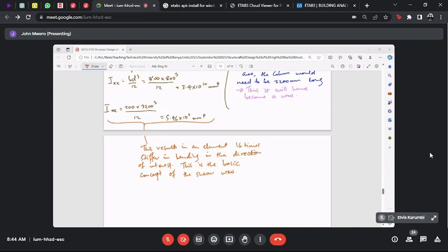And if the period of vibration changes, coming back to just this simple standard that we were looking at, the Kenyan Earthquake Code, if you change the period of vibration, you change the earthquake force. I have started making an attempt to answer this question by saying it's a very complex question to respond to. But I've thrown to you some thoughts that would help you to start thinking in the direction of what would be the effect of changing the form of the structure.